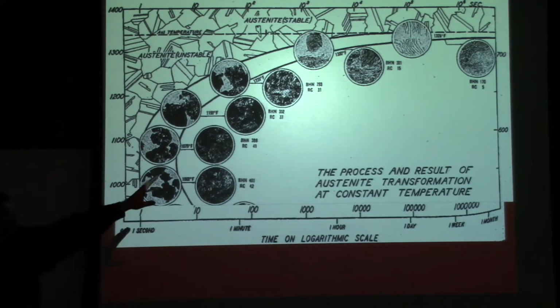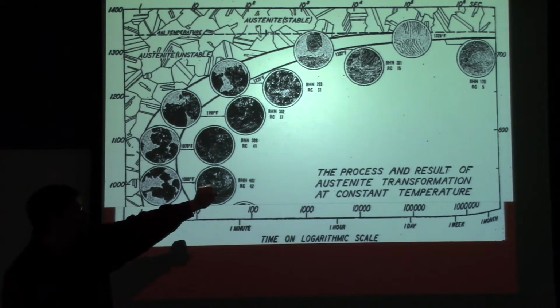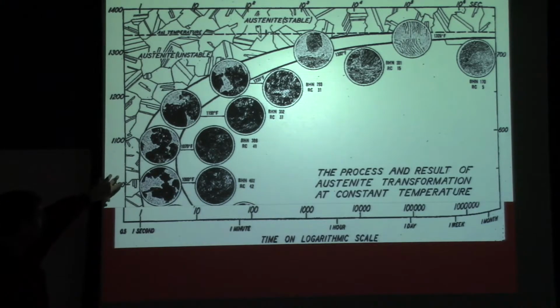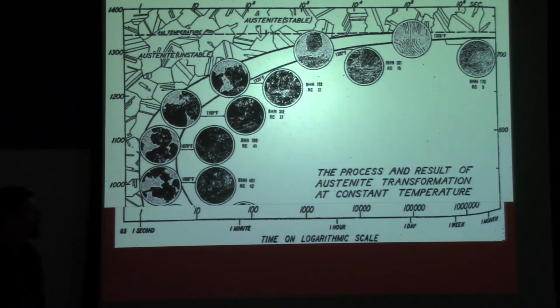But you can see on the extreme right-hand side, we're at very soft hardness values, Rockwell 5. Over here, at this end of this curve, we're in the low 40s. So quite different hardnesses.